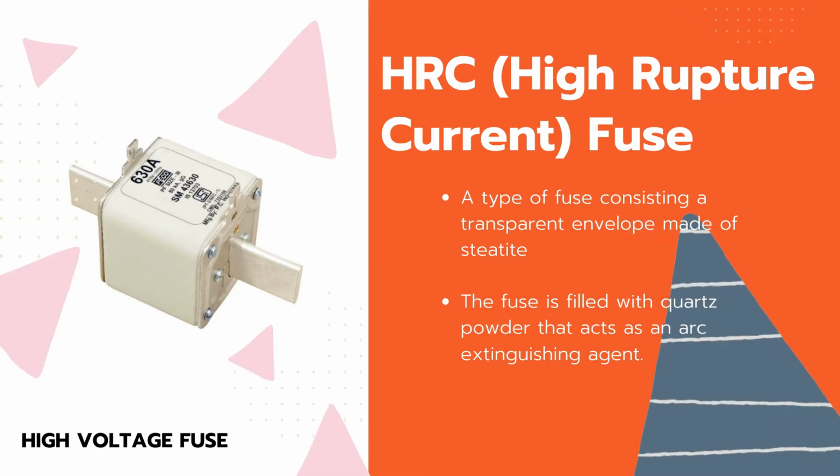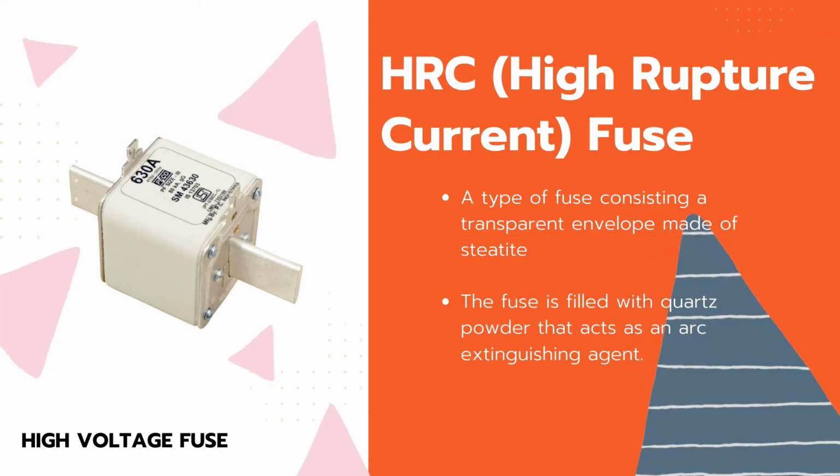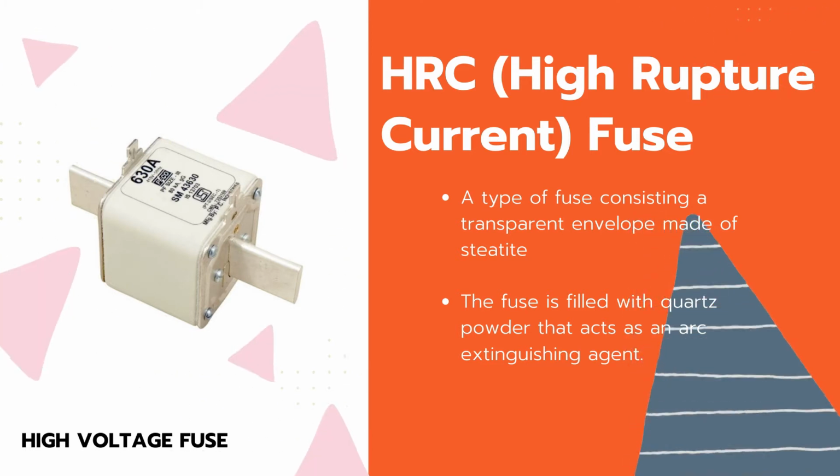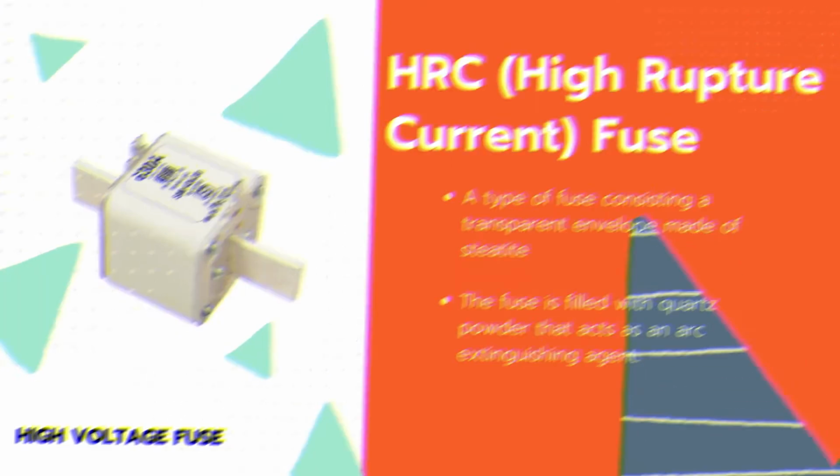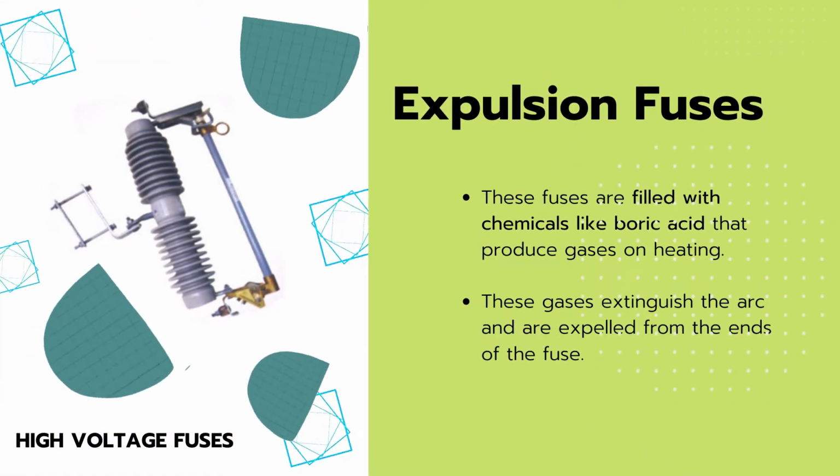The fuse is filled with quartz powder, which in case of liquid-filled HRC fuses is a non-conducting liquid like mineral oil, that acts as an arc extinguishing agent. These fuses are used for very high fault currents.